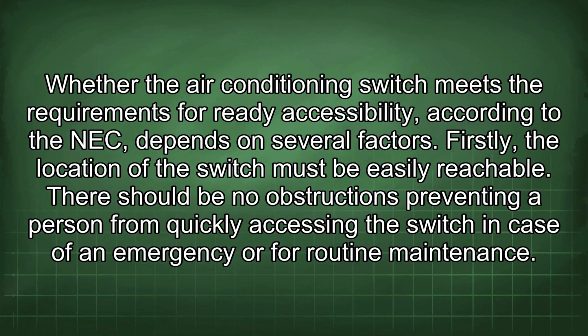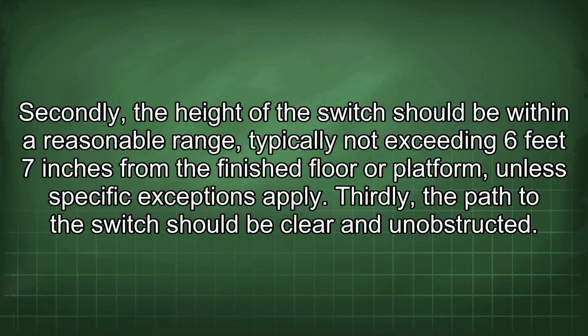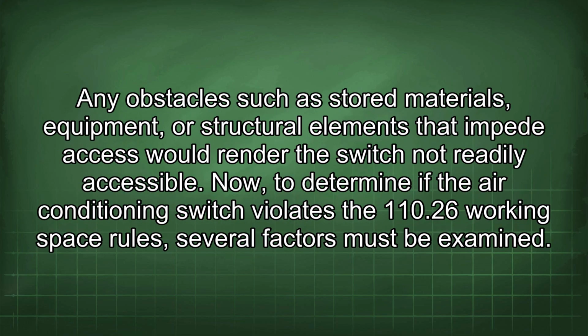routine maintenance. Secondly, the height of the switch should be within a reasonable range, typically not exceeding 6 feet 7 inches from the finished floor or platform, unless specific exceptions apply. Thirdly, the path to the switch should be clear and unobstructed. Any obstacles such as stored materials, equipment, or structural elements that impede access would render the switch not readily accessible.